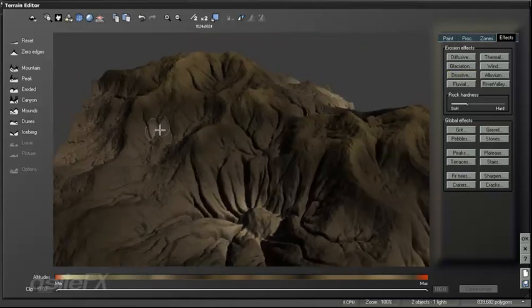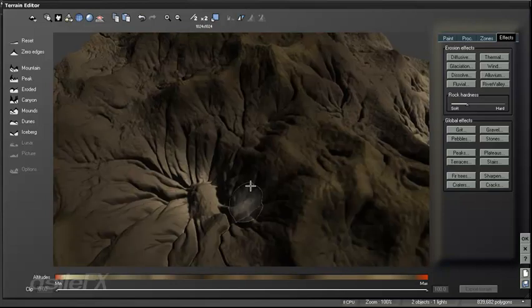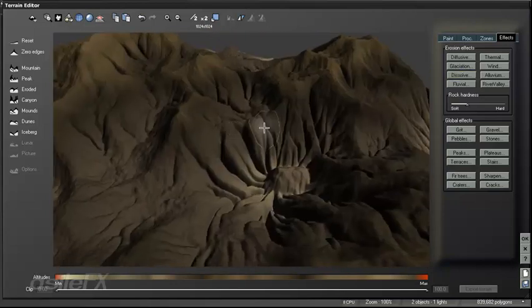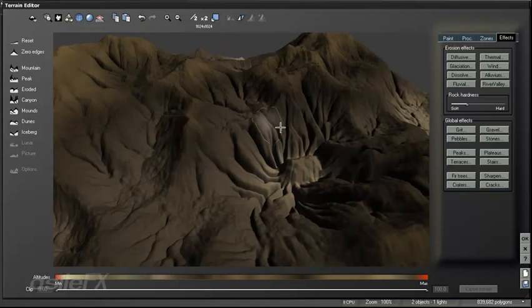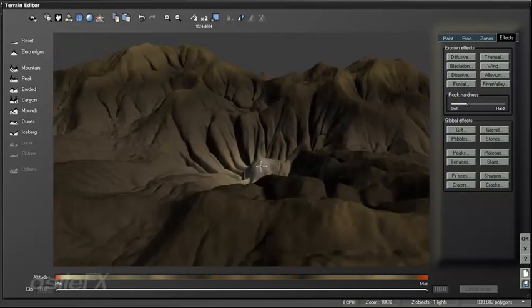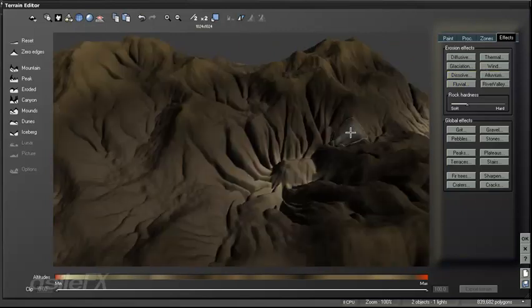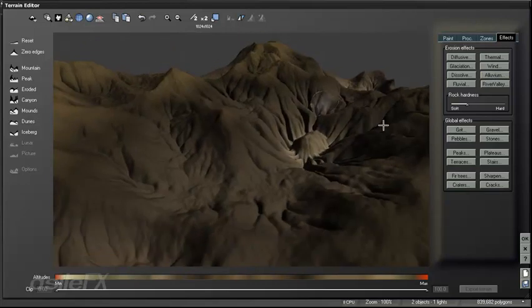Because in fact, these layers are working independently, and really we're just using layer 2, the procedural altitude, to modify layer 1 and kind of extrude from there. In a way, it works kind of like the displacement does with sculpted geometry, except that it only extrudes on the z-axis or the up-axis, rather than being able to move on all axes.